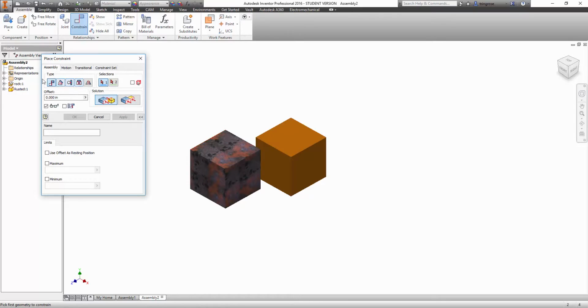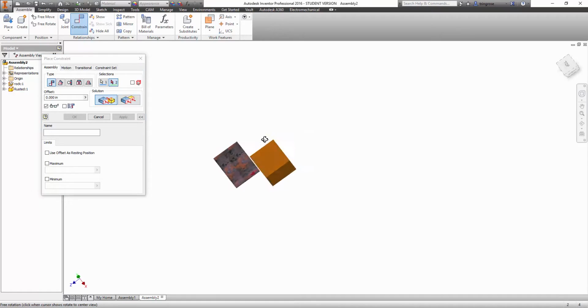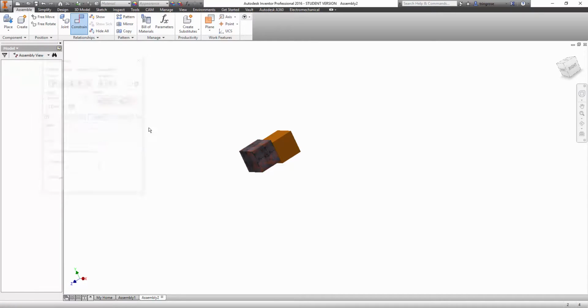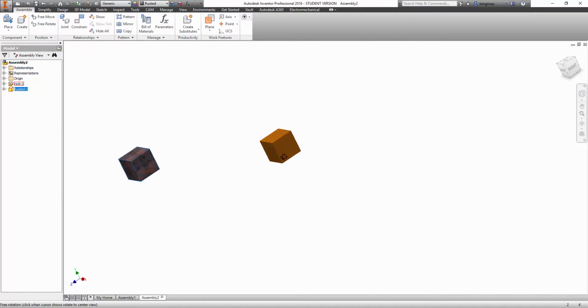But what we'll do is we'll say, okay, I want this face here and this face here to be stuck together forever. Apply. Now, while it looks like I can move far away and that these faces aren't stuck together, in reality, if I turn and look, it's just moved far away in space. They're still connected. For the most part, when it comes to constraints, we're going to need at least two, usually three, to lock two objects together.